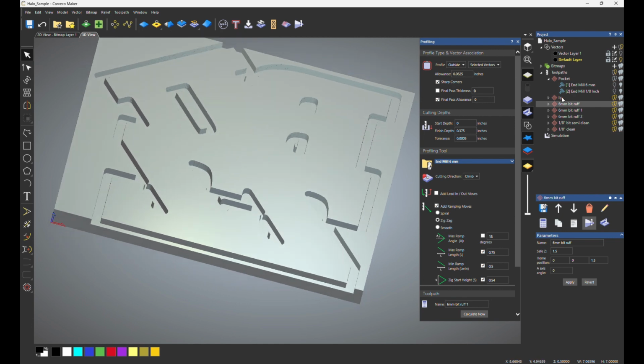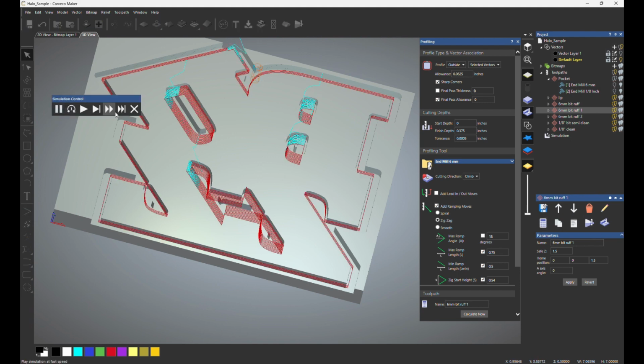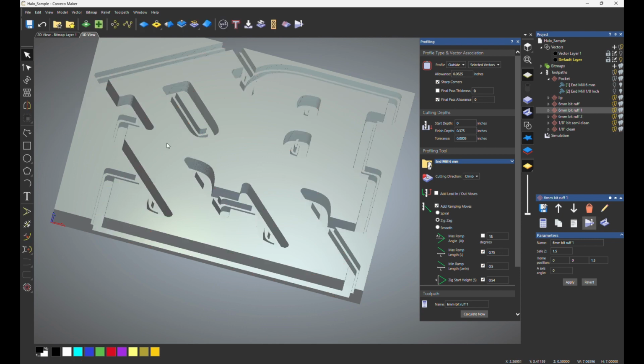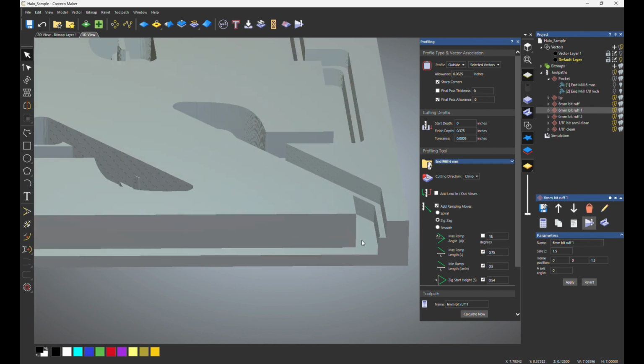It won't get too deep just to cause a lot of rewelding. So then when you do the second pass here, it moves in a bit and it goes a little deeper. So what that does is give room for the chip to leave, right? It's not just trying to suck it up the entire channel where there's no room for it, so it's rubbing against the walls. What this does is it only has to lift it up this little bit, and then it gives lots of relief. Then we do the third one, same thing.